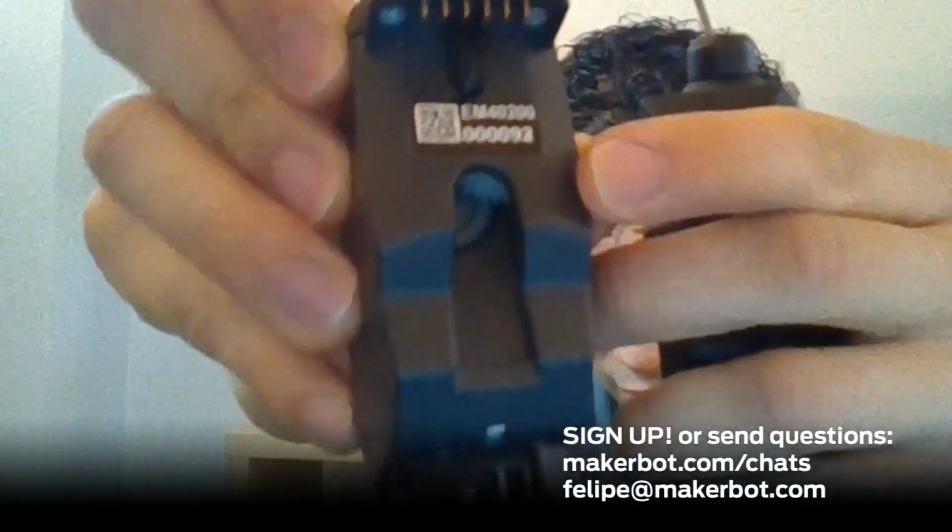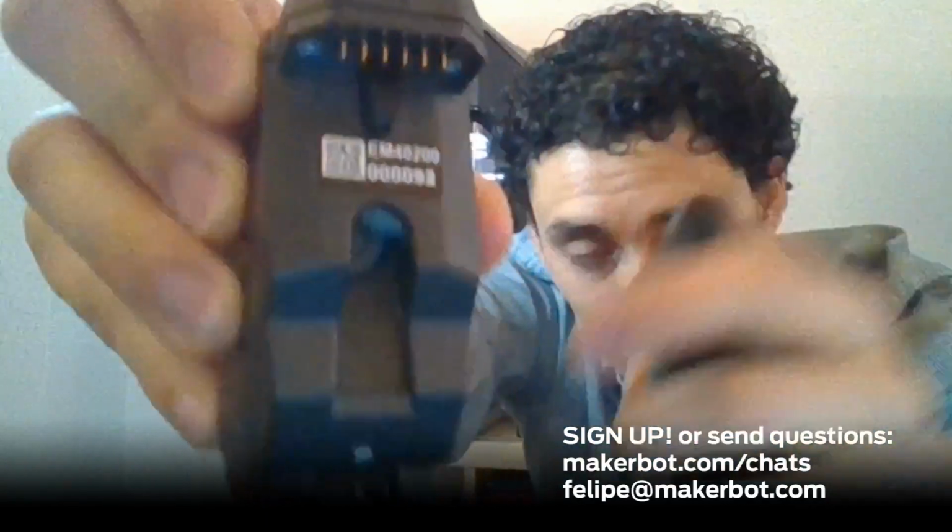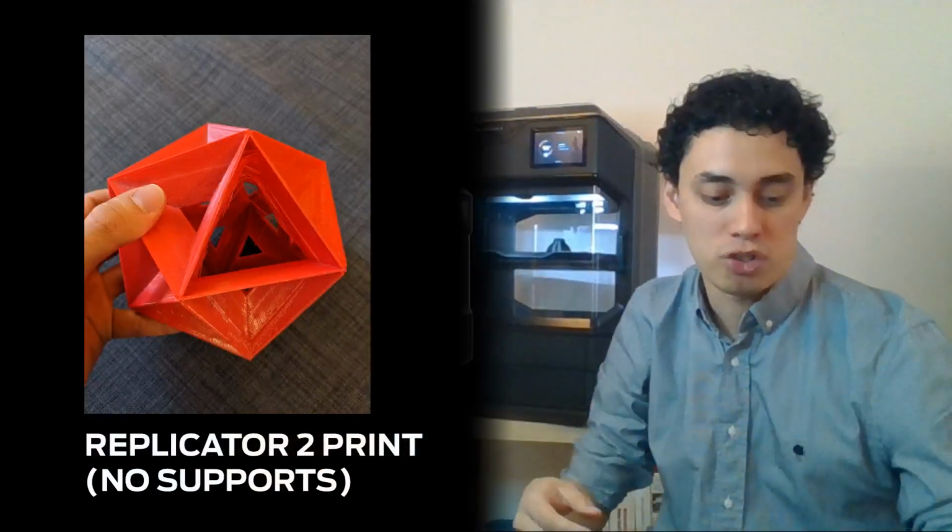Many of the newer extruders, specifically on Method, you don't see this in many desktop systems. Many desktop systems, I've seen that the extruders are kind of this big. They don't have a lot of smarts on them, to be honest. It's basically just a heating element that pushes filament through, and it doesn't even have the motors integrated to them. So with the newer extruders, like this one, you can actually see here, there's a whole gear set integrated into an extruder that helps you push material at a more even rate and a more controlled rate than traditional desktop systems.